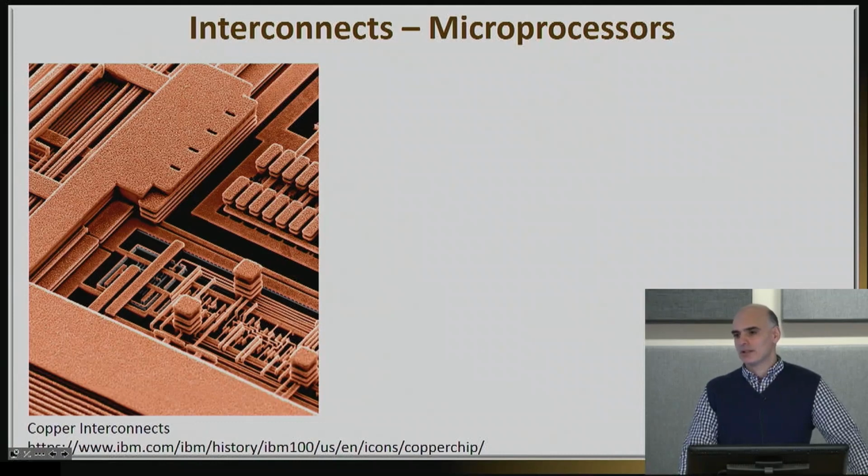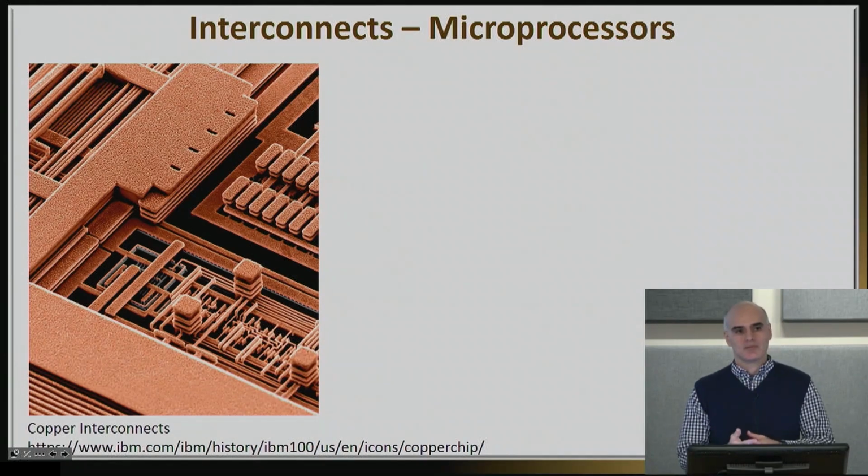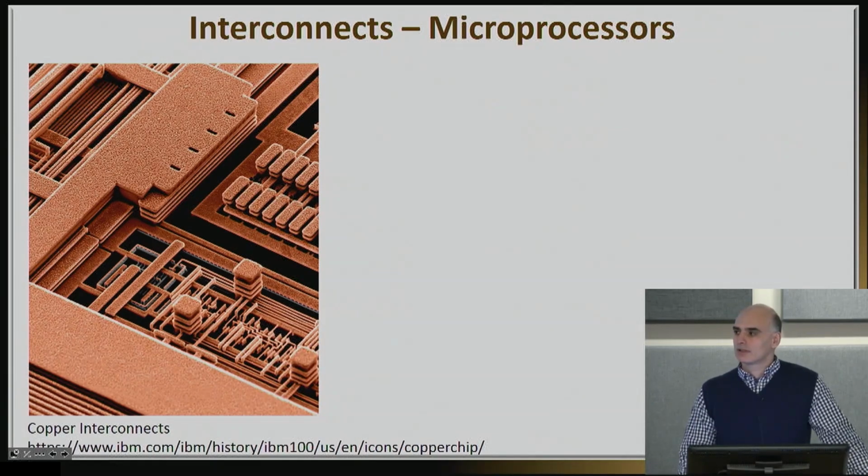So we're talking about a ton of interconnects, a ton of distances that signals have to propagate through. And those interconnects have to connect billions of transistors in that type of chip. And those are multi-layer. In a modern VLSI circuit, you will have between 13 to 15 layers of those interconnects. So it's not like a single street highway. And actually, it's those interconnects that will slow down your circuit.